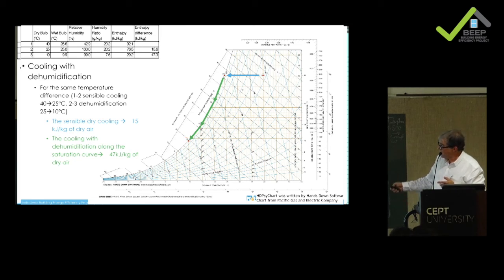So now if you look at the ratio, and if you think of the enthalpy difference, right? So for 15-degree difference in the first phase, this is the enthalpy difference we get, right? And now this is what we have for the second 15-degree difference, but with the phase change, with the condensation of water in the cooling coil. And so it shows what?